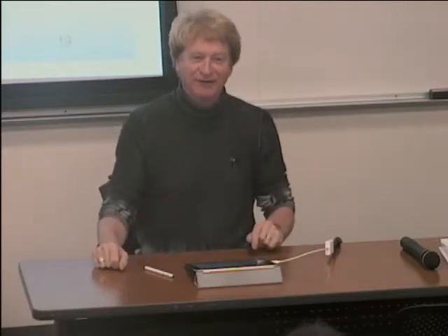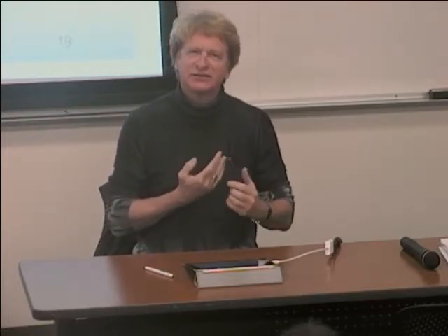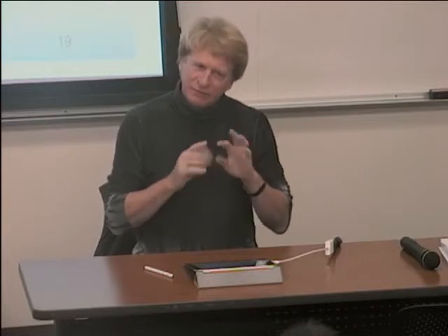It's not going to be pretty. You have a memory cell and a lot of logic in your block, because you're going to have adders, at least 2 adder cells. There's going to be some other multiplexers in there. There might be a comparator, all depending on how you designed your logic. But there's a lot of things you can play around with. Write down the Boolean expressions and start manipulating them, because you will see there's some interesting things you can do. It's a fairly rich problem, so it's going to give you some opportunity for creativity.